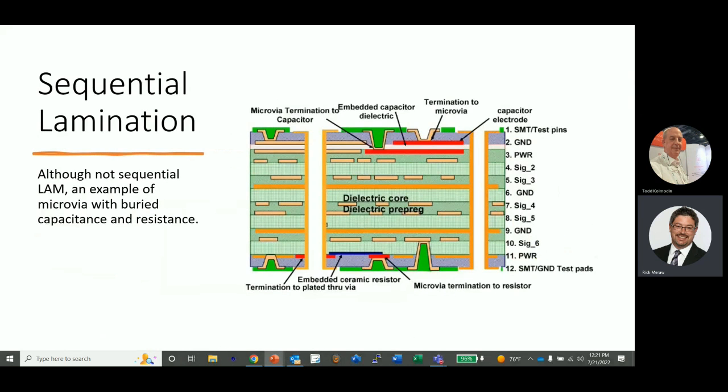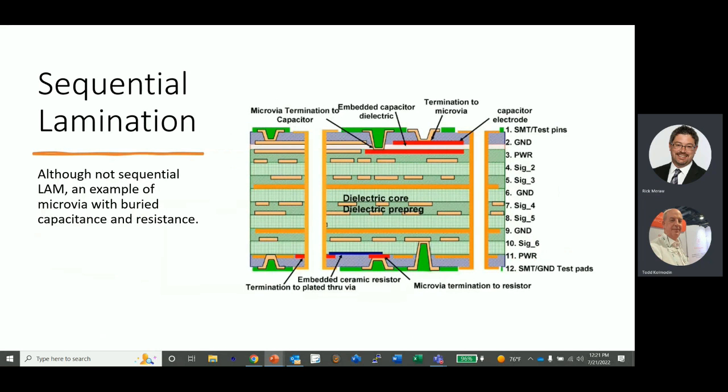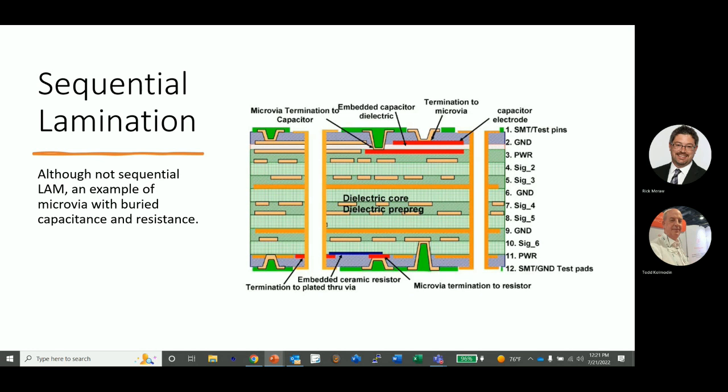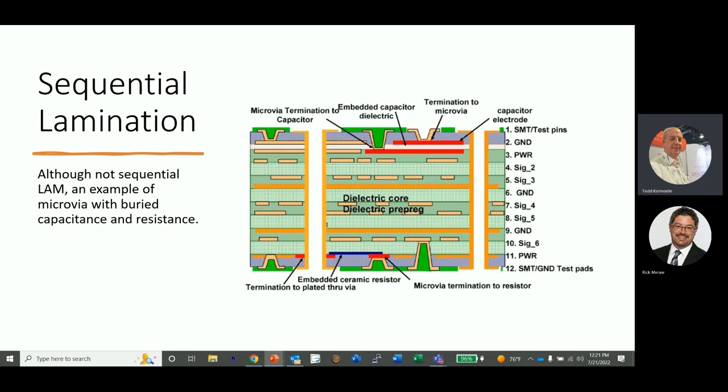I know a lot of companies call it sub-assemblies too. Sure. It's an assembly, right? It's part of an assembly, but it goes with the entire package later on. So it's only parts of an assembly, and you need more parts of the assembly to make the final PCB at the end. Exactly. And what happens a lot of times in the manufacturing process, your sub-assembly, your subpart will have its own part number designation, and some companies have different names for them. They call them the child part or the subpart. Then you have a parent part, which is the final version of everything all laminated, drilled, and plated together.